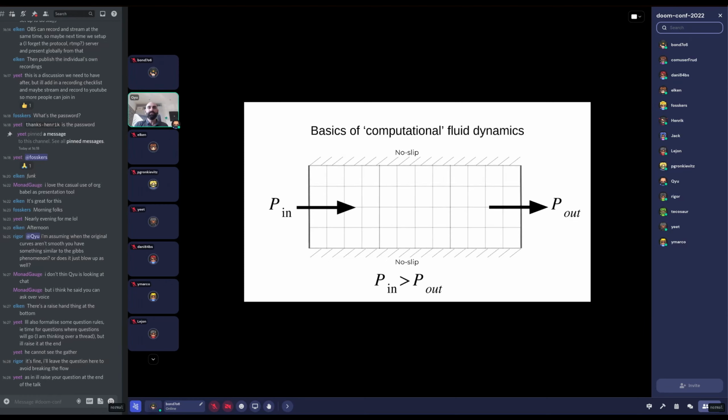And to give some type of idea, this is something that we could, for instance, do analytically. Then we need to have our boundary conditions. So this means pressure in, pressure out, and the pressure in has to be higher. So the velocity will go in this way. And then we say that we have a wall here, which means that there is no pressure gradient crossing this wall, of course, and also that the velocity of the fluid on the wall itself is 0. And just knowing this information, if we simplify it to 2D, we could actually solve this thing analytically. And this is essentially where I want to start part 2 of the talk.